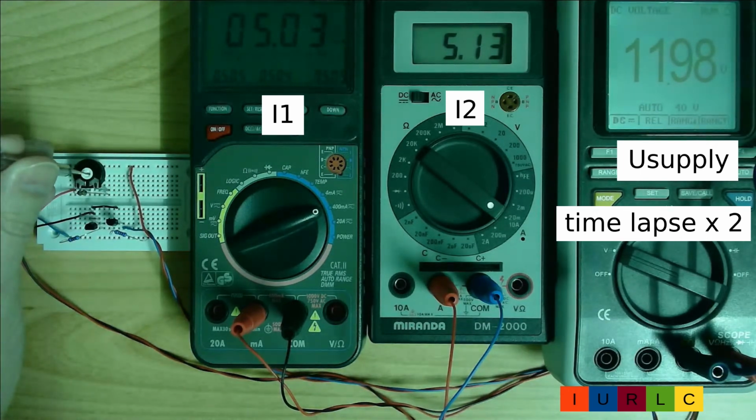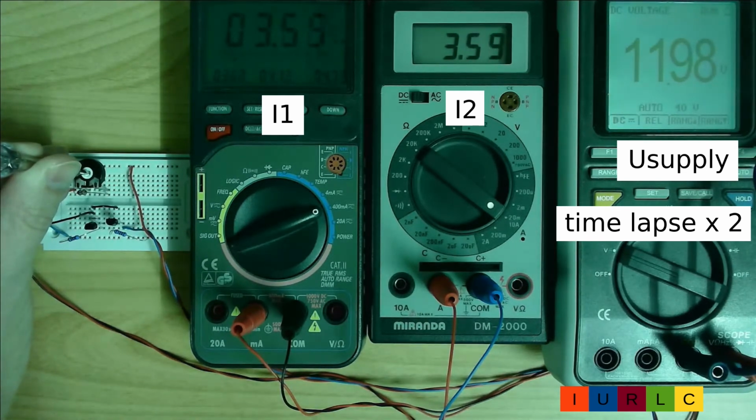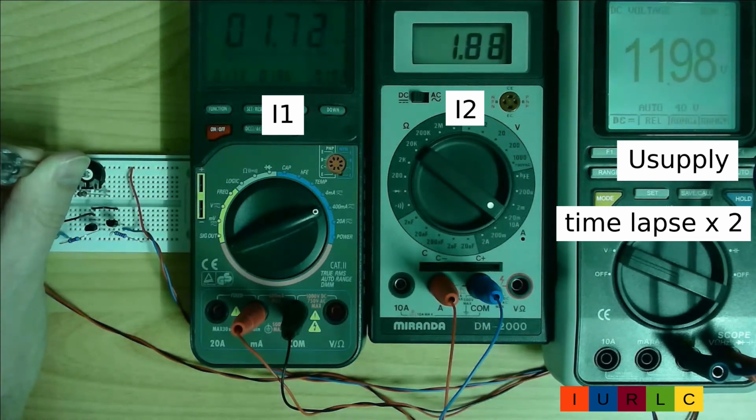I will now reduce the current I1 to 1 mA, which will lead to a voltage drop of only 200 mV at the emitter resistors. And this low voltage drop will cause a bigger error in the discrete current mirror.